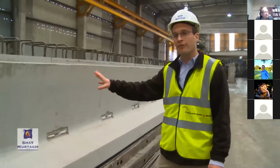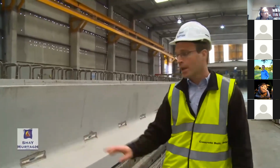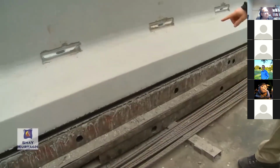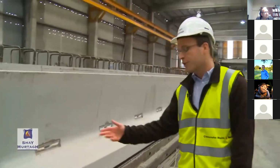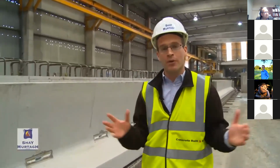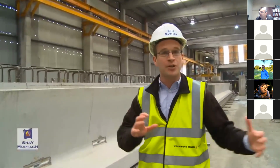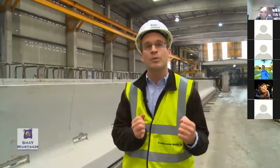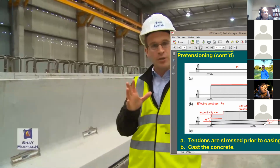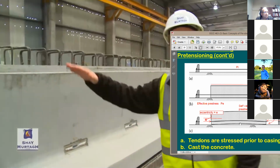Okay, so this beam is one of our finished products. This was actually cast not long ago on this bed itself. Now, you'll notice there's a bit of a gap between the soffit of the beam and the actual bed itself. This is a result of what we just spoke about. When we apply that compressive force from the pre-stressing tendons, pre-stressing strands, not only do they apply that beneficial compressive force to the beam, but they also apply a moment that relieves the moment applied under working conditions. So this moment that's applied by the pre-stressing operation results in the beams actually cambering up.